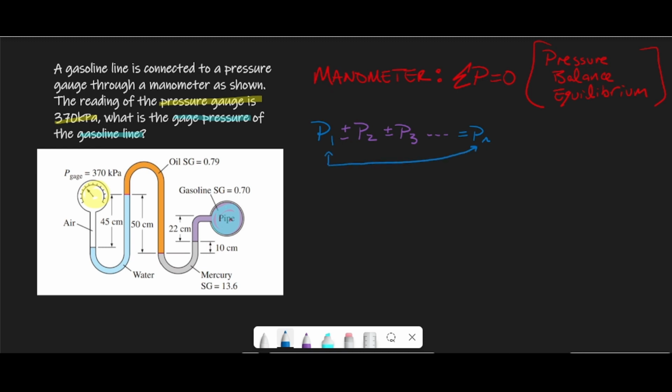All right, let's talk specifics. In fluids, there are different types of pressure, which can be super annoying, but it is what it is. For manometers, you've got 2 types, the terminal pressures and the fluid column pressures. The terminal pressures are the ones that are measured by a device and are normally what you solve for. The fluid column pressures come from the weight of the materials.